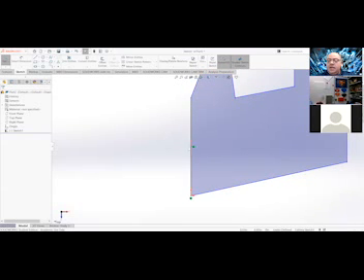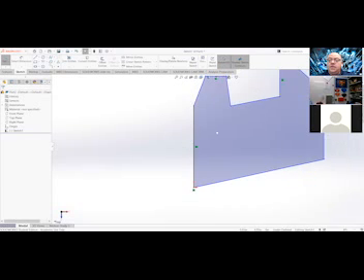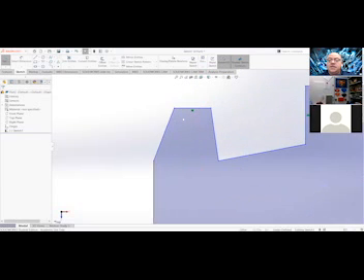This green line now, we saw it with yellow when we were drawing the line, has a vertical line that says this line is perfectly vertical. In the same respect, this line is perfectly horizontal, but it is not fully constrained because it's still blue. And I need to get all of my lines to black. That's my goal. I want all my lines to be black.